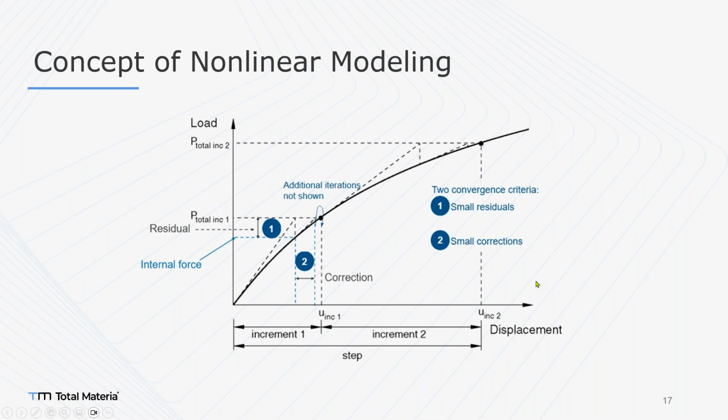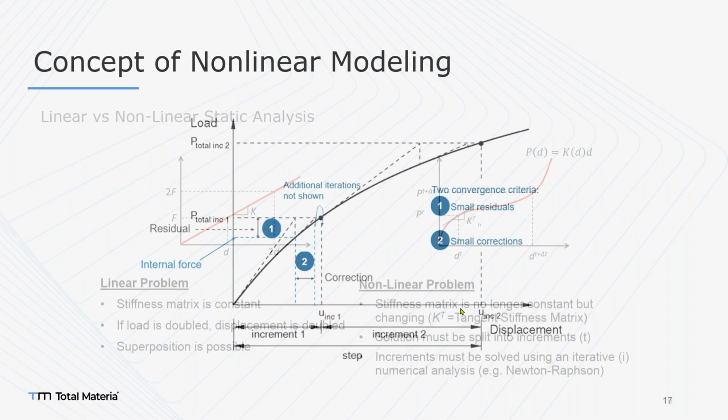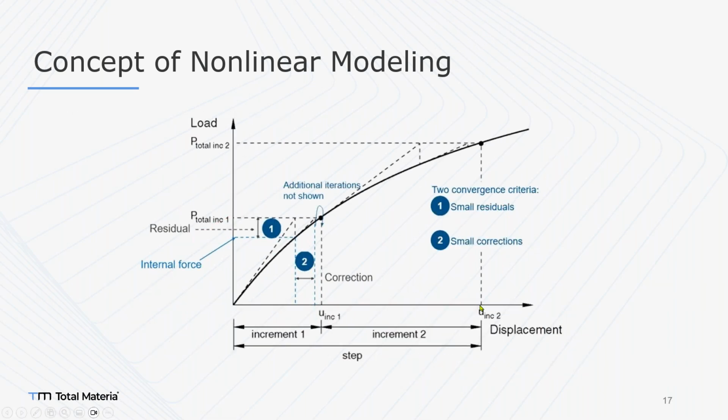So Bart mentioned the increments, the iterations under the increments actually. Newton-Raphson has iterative solutions, iterative numeric analysis in here. So we have some increment method. We need to have increment method because we cannot just go to this point in one jump. So we need to reduce our total load.